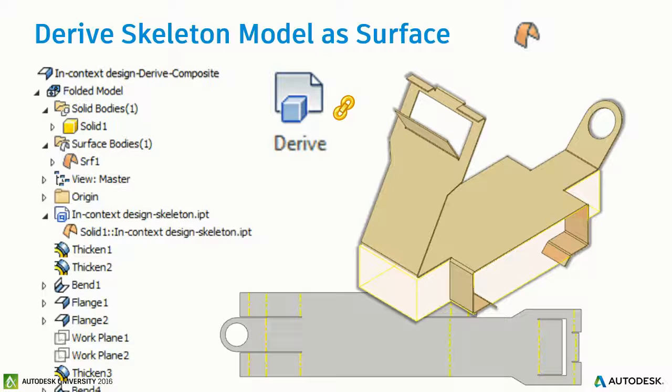Another thing is that you can just do flat pattern in this part. With the currently existing multi-body support in Inventor, if there are multiple bodies in one part, you are required to make parts for each solid and then do flat pattern.